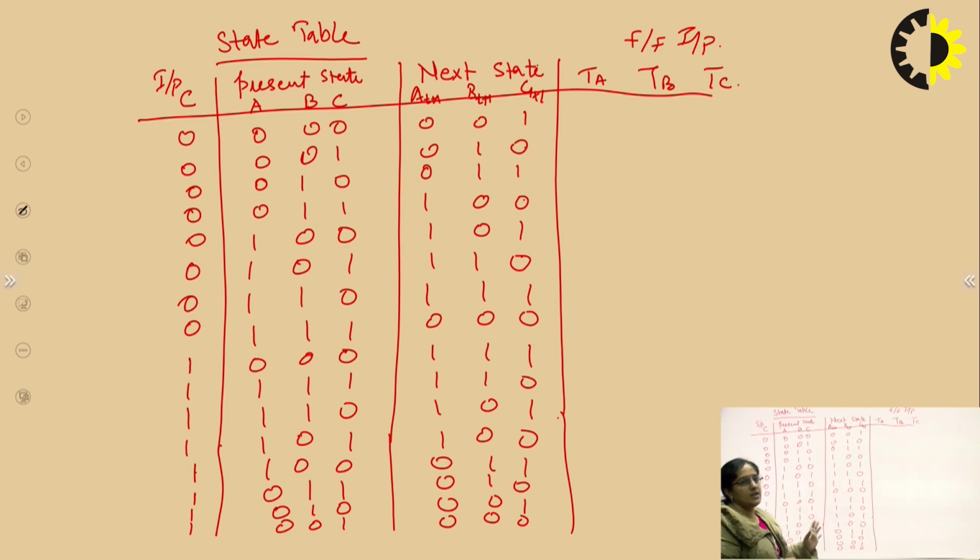In this way we have a sequence for up counting and a sequence for down counting in the same flip-flops. If we only have to design a 3-bit up counter, we use the up state table, and for a down counter, the down table. From this table, we refer to the excitation table of the T flip-flop to find the outcome.